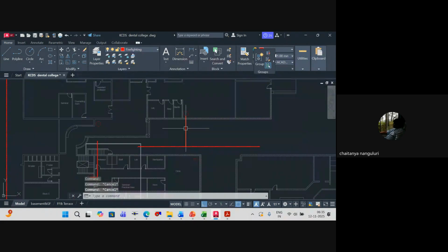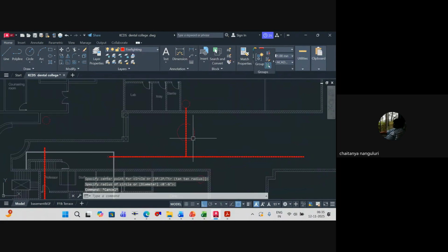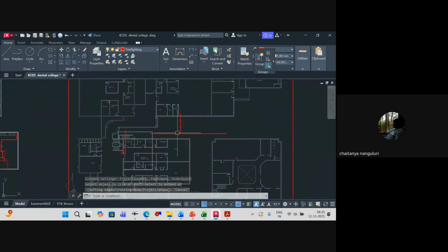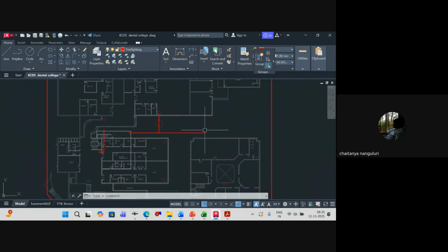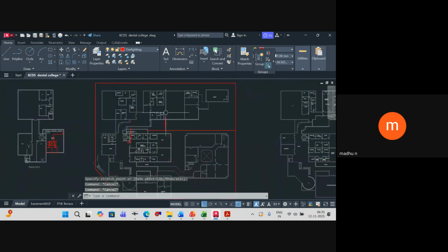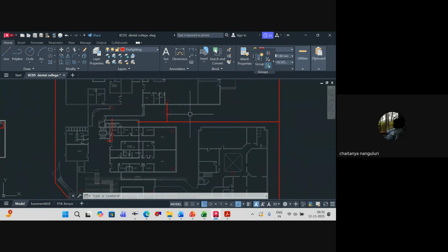Then what we are going to do, we will provide an alarm valve at this location, and then we'll provide an isolation valve at this location. External to the building, you will provide all these provisions. Understood? Alarm valve only for that zone? No, for this zone also, you'll have a separate alarm valve. You will provide isolation valve and alarm valve, at least isolation valve external to the building, so that firemen can operate that valve. You'll isolate it manually from outside.